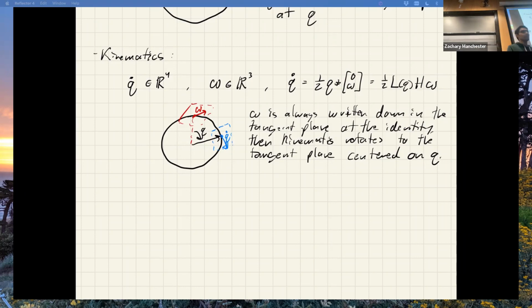But if I try to integrate it, you can't actually. I can't do the integral of omega dt. That doesn't actually mean anything. It's not a good thing to do because you don't get this additive stuff. The right way to do it, if I were to integrate omega into a quaternion, I get this. We talked about the rotation matrix version of this too, which looks very similar minus the 1/2 last time. The Euler angle version of this is really, really nasty and complicated. It has a bunch of trig functions and a matrix that can go singular and all kinds of bad stuff.